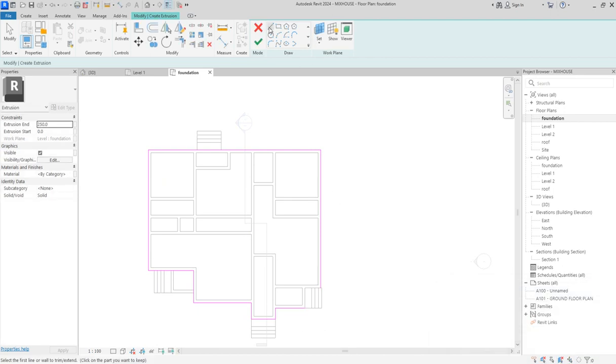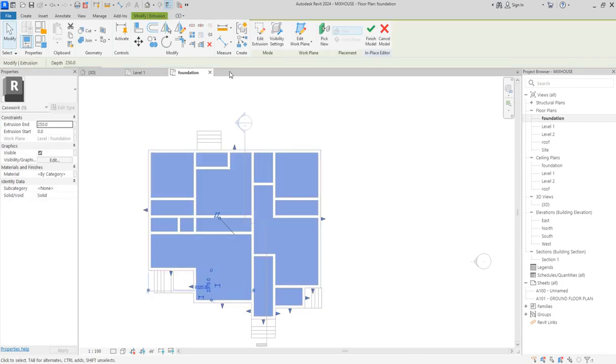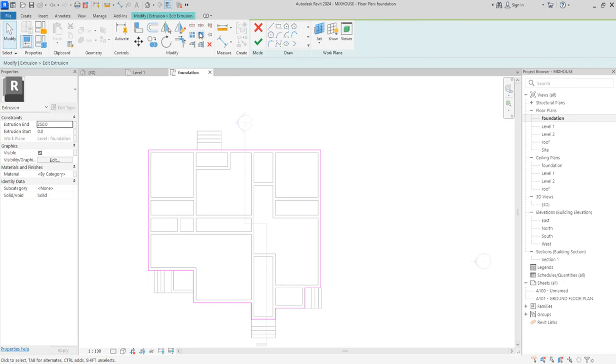Continue, and then you draw this one, you click finish. So edit again. Here what you need to do is offset. Create an offset on this and say 700 will be okay. So let's use 700 for that position. Click and click. Now you have a double line in position.